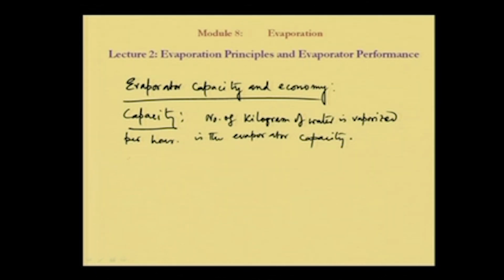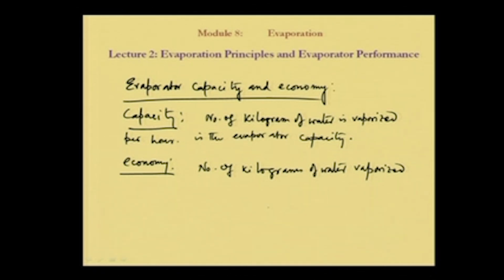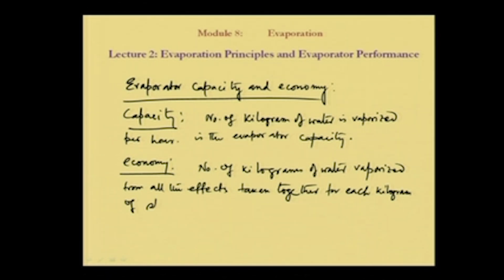Similarly, there is the terminology economy. It says that the number of kilograms of water vaporized from all the effects taken together for each kilogram of steam fed to the first effect.